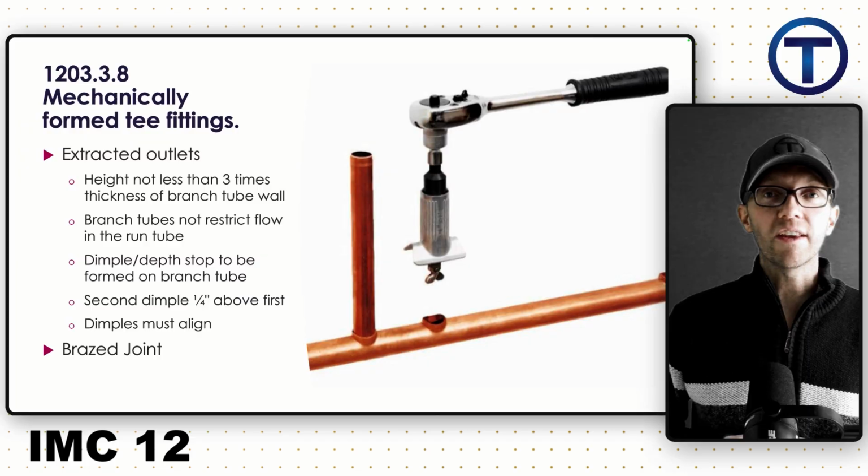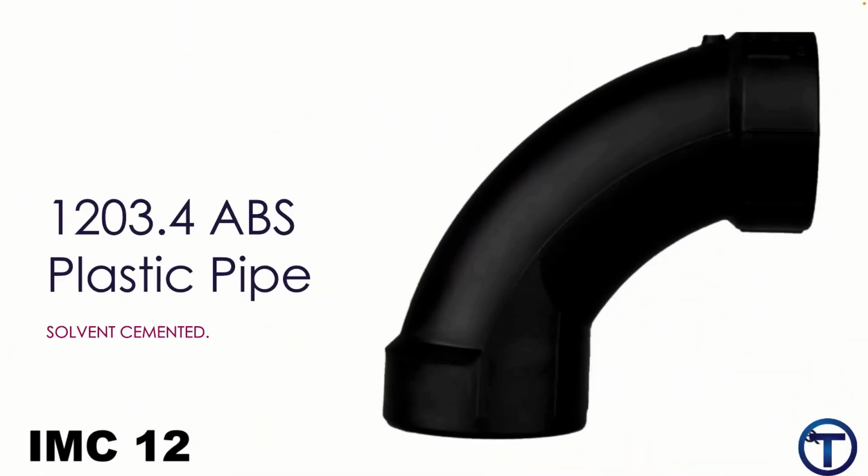Now that we've looked at some of the methods for joining pipes together, let's go through the different pipes that can be used in a mechanical system and see which of those methods apply to which types of pipe. We'll start in 1203.4 with ABS plastic pipe. Plastic pipe should be solvent cemented together. That's the only option they give us for ABS plastic pipe.